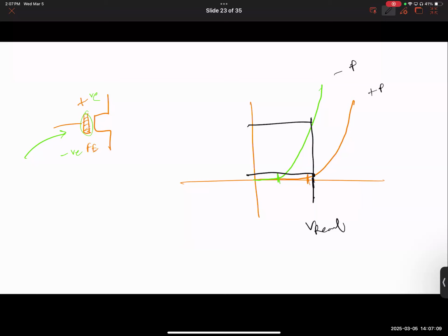Does that make sense? So when you apply a voltage, you get low current, meaning it was storing so-and-so polarization. But if you get high current, it's the opposite polarization. And polarization could represent 1 and 0. And that's how you read. So I'm giving you the overall principle of operation for FeFET-based memory. Do you see that FeFETs can, in an interesting way, use the polarization and transfer it into the current of the transistor? Okay, I'll tell you the beauty of this approach.